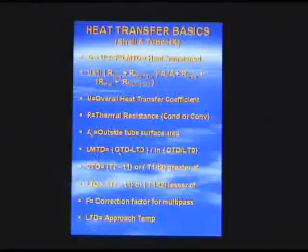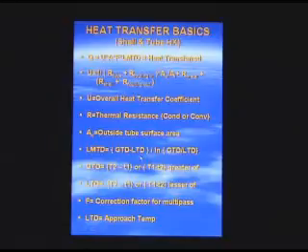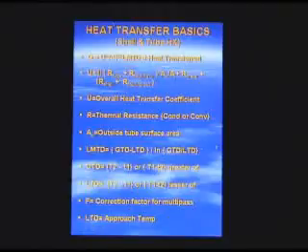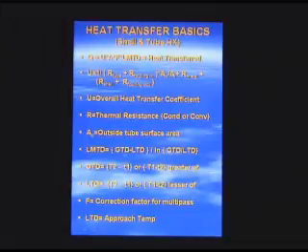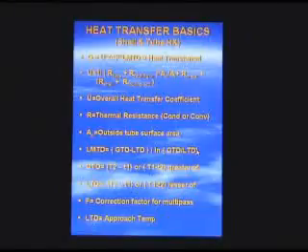That stands for the greater temperature difference minus the lesser temperature difference. I probably should have a better sketch of that. I didn't include it, but basically when this term is evaluated, that is the effective temperature difference from the inlet to the outlet that the two process streams see, and it is the driving force to promote the heat transfer between them.